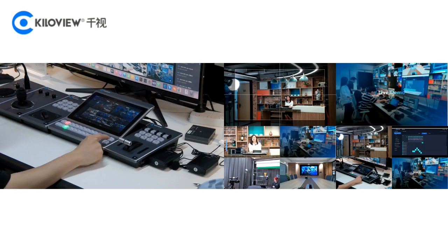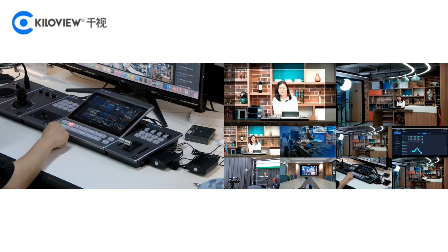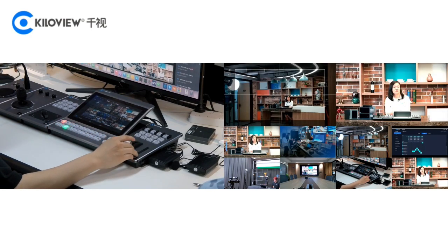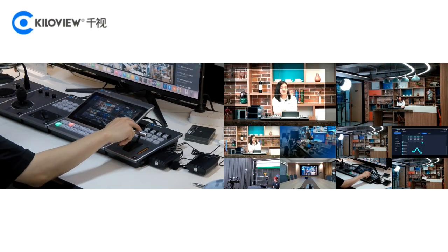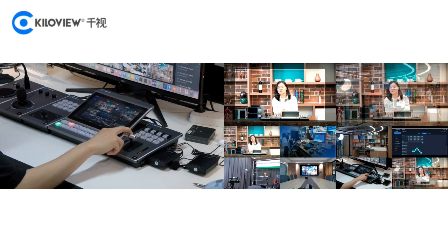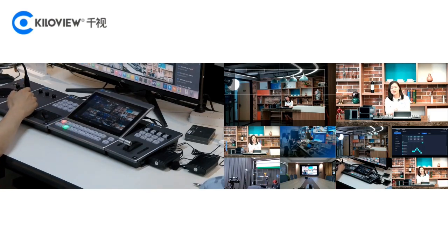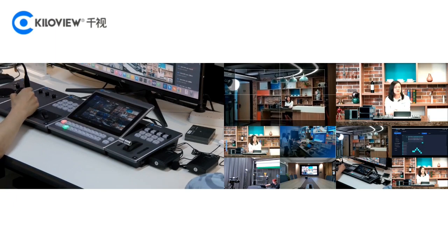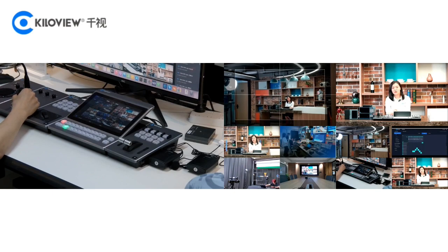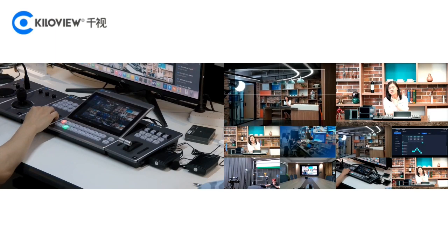From the right part, you can see we are doing the operation, and simultaneously all those signals are switching. Or you can use the T-bar to take the videos, and if you move it slowly, you can control it for the fading effects. And of course, if you select any video source from a PTZ camera as the preview, you can use the joystick to control the PTZ camera. You can pan, tilt, zoom, or if you just need to zoom in or zoom out, you can also use our zoom deck to do that.